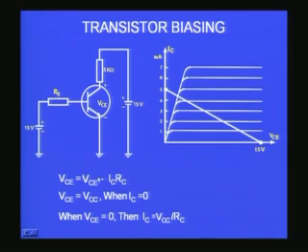So, this is characteristic of a particular load, or the resistor that I connect here. Therefore, this is called the DC load line, because it is now under DC condition. I have not applied any alternating voltage yet. So, this is the DC load line, that is what I showed here.